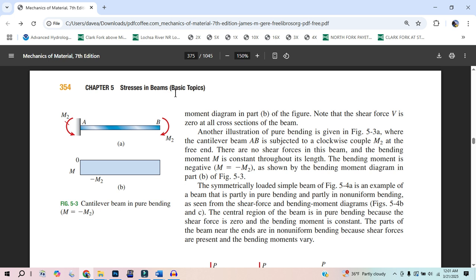You know what I mean? Just for all intents and purposes. And then that has to be coupled with a positive moment. So we have a negative moment and a positive moment. That's why our net moments are 0. But one is in this direction, and the other is in that direction. And those two moments have a tendency to cause a frowning face. So when we do our internal cut, we should draw it in the positive direction.